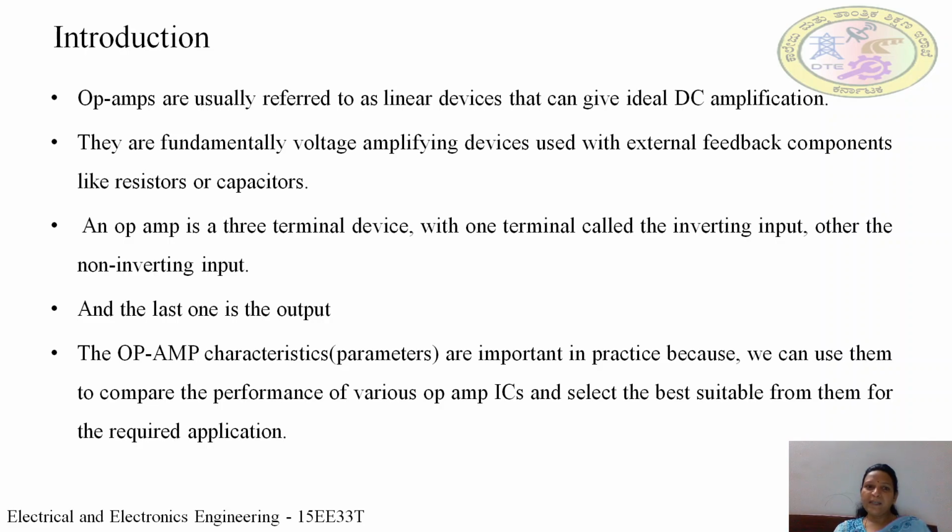They are basically used as voltage amplifying devices, and they are used with certain external feedback components like resistors and capacitors. It is a three-terminal device having two input terminals, one is the inverting input, the other is the non-inverting input, and one output. It also requires two DC supply voltages, a positive supply as well as a negative supply voltage.